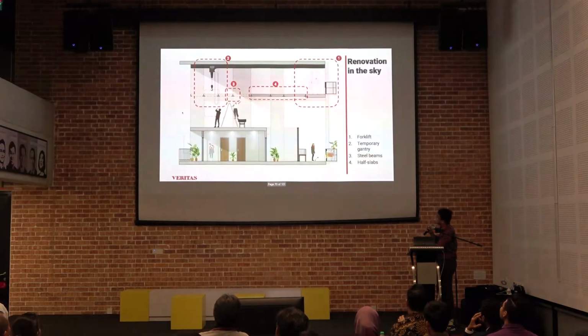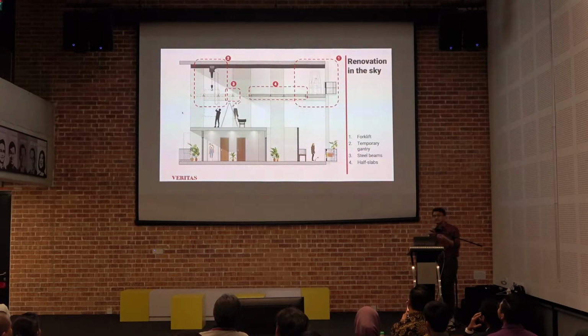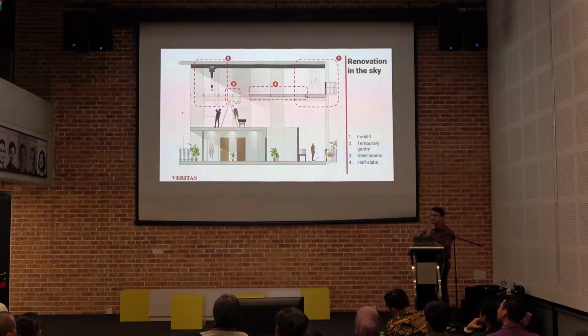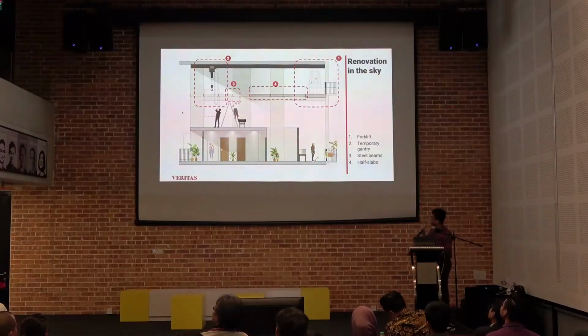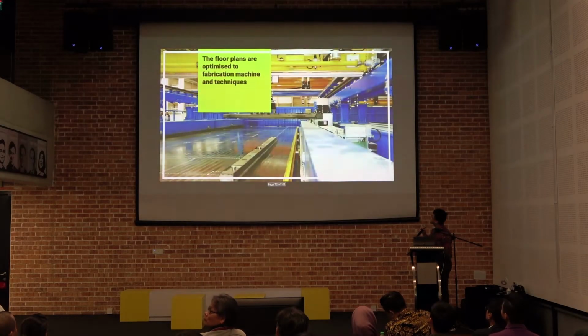So a lot of the details were important. We really thought it's important to have steel junctions so that you don't drill into the concrete and disturb a whole community while you're renovating. So a steel member would allow the first few slabs to be installed without creating such a racket.